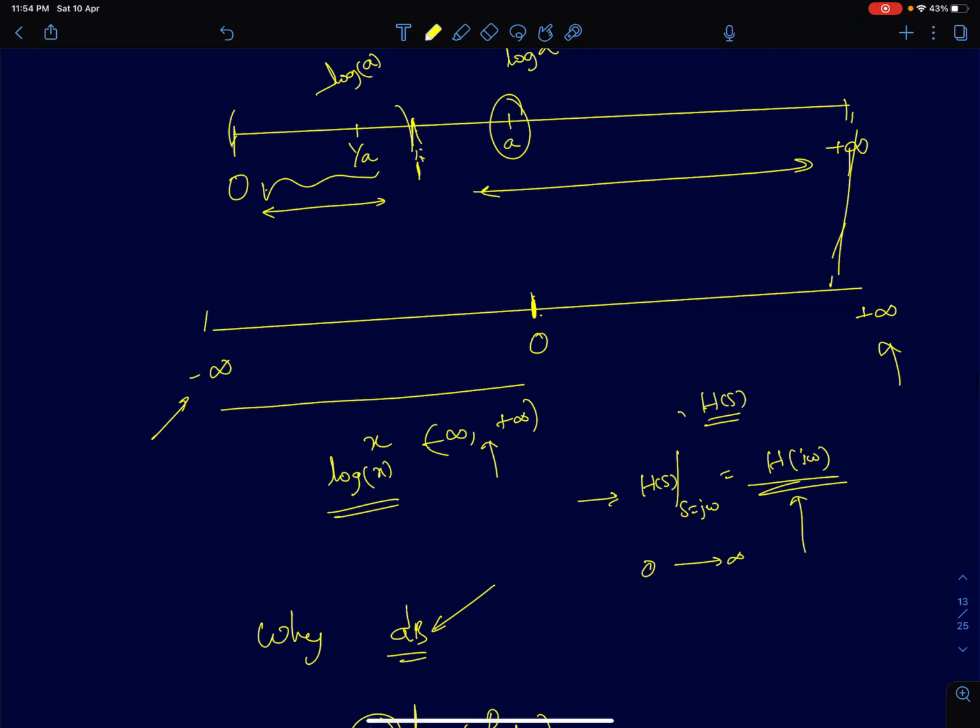Hi everyone. In the previous lectures, we started with our discussion on the frequency response of amplifiers. We said that most amplifier circuits can be linearized around a DC operating point, and then the amplifier equations can be reduced to simple linear differential equations. Once we have linear differential equations, we use Laplace transforms to solve them because linear differential equations become polynomials in s, and we can use the rich literature of algebraic theory of roots to understand those